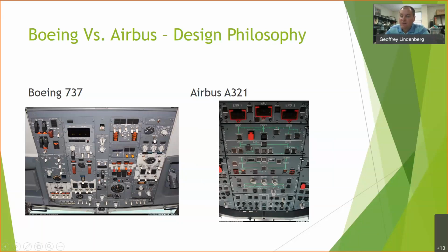Boeing tends to lay stuff out by system. So here's your flight control system, navigation. I want to say this is fuel, if I remember right. Okay, and it is still left boost pumps, right boost pumps, center boost pumps, and then fuel feed to your engines. You have pneumatics over here, so left bleed valves, right bleed valves, left pack, right pack, air conditioning.